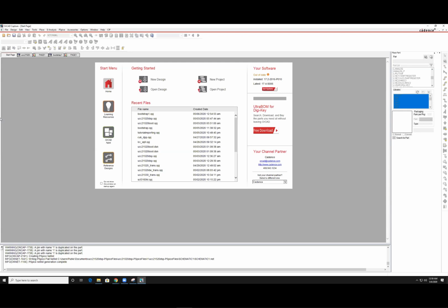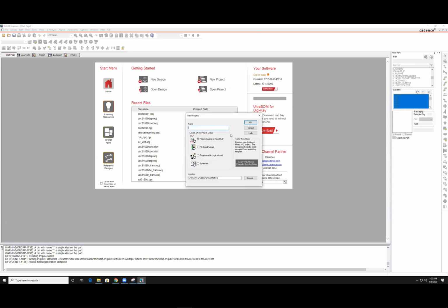Please watch part 1 of this series to make sure you have properly imported the components we will be using in this video. First, we want to open up OrCAD and create a new project. Go ahead and name your project, select the first option here, and pick a location to save it. Hit OK and click blank schematic.